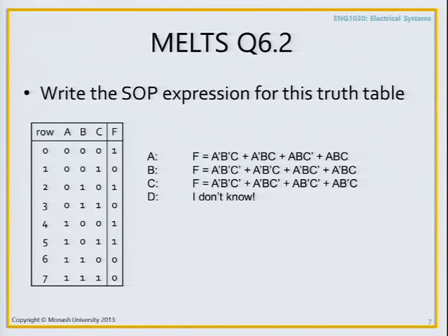Inverting these symbols in this SOP, I just did not get. Why are you doing a complement? Yep, so if you have something like A prime, B prime, C prime, why am I doing that? Because this will give a 1 if and only if A is a 0, B is a 0, and C is a 0.